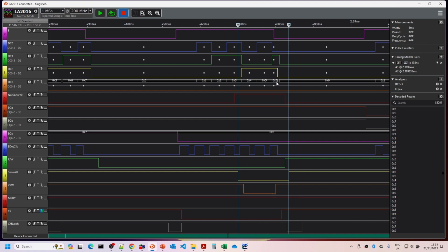And then what we would expect to see is, when we did have the MRDY going low here, we would expect to see this be extended by 1 or 2 CPU clock cycles, which is, at 8 megahertz, 125 nanoseconds. So we might see it extend up to there, and under that circumstance we would see some of these things moving around, and we'd also see here 7, 8, 9, 10, 11, 12, 13, 14, 15, potentially up to about 12 or 13 coming up here. So that's what we're going to do in a minute.